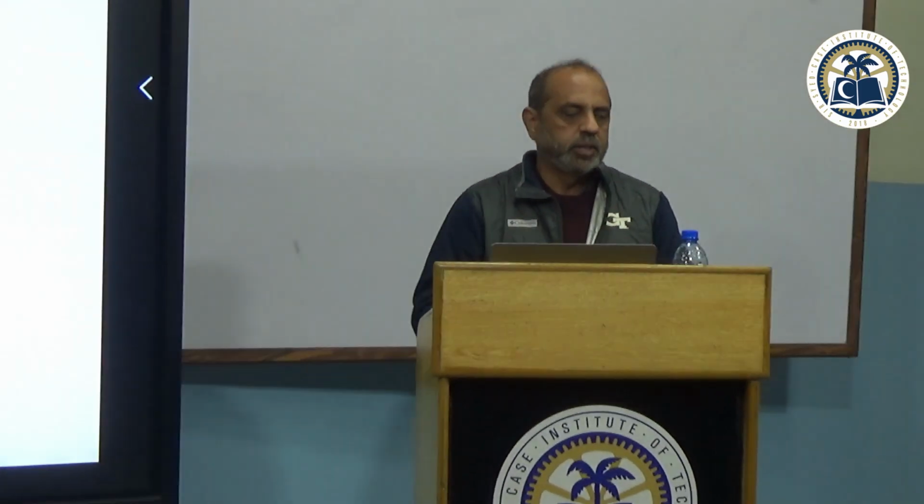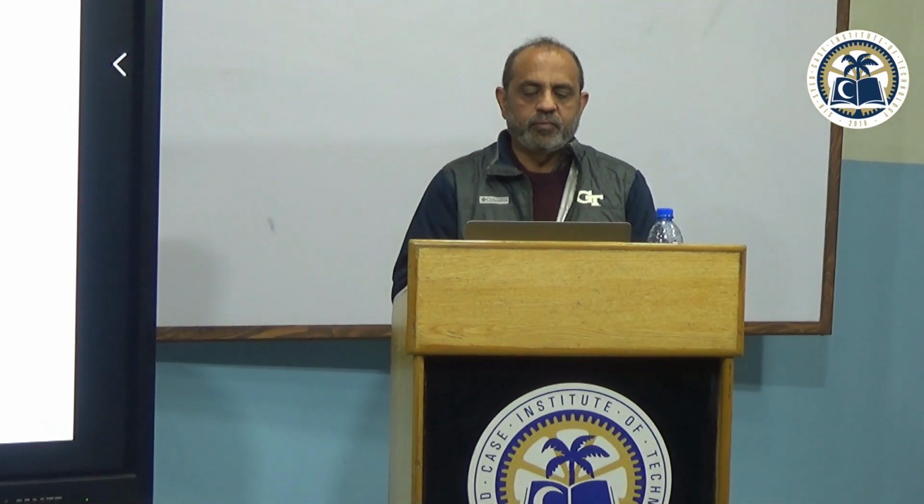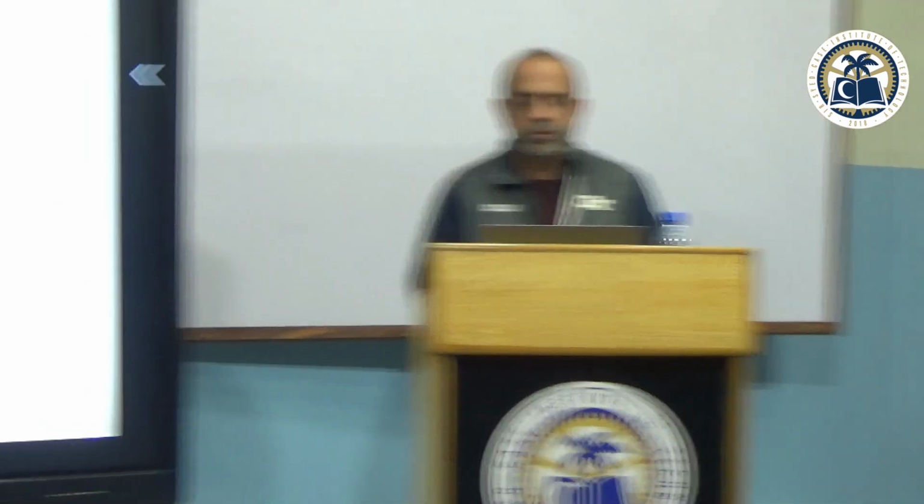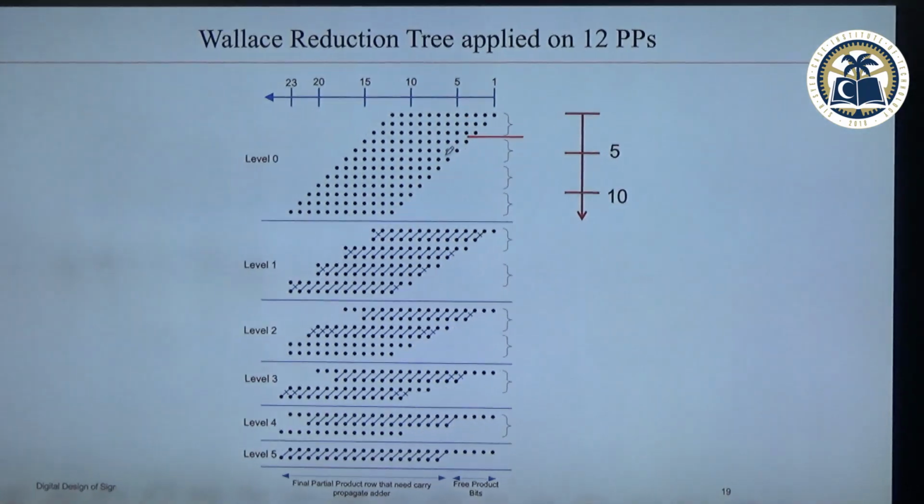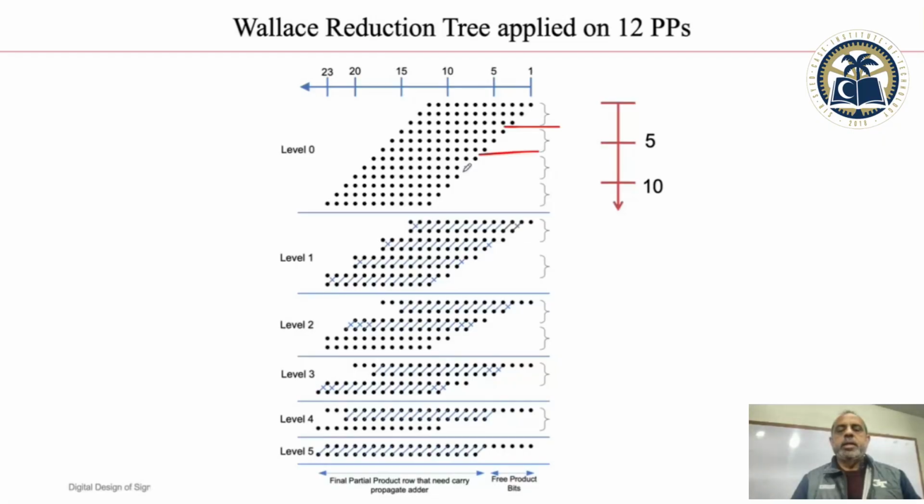But interesting is the Wallace tree. Wallace tree is where you have all the 3 layers together. So you have these 3 layers, and then you have these 3 layers, then you have these 3 layers, then you have these 3 layers. So in one go, putting a full adder layer would reduce them into 2, 2, 2, 2. So 12 would get into 8, right? 1, 2, 3, 4, yeah, 8. So from 12 layers with a full adder delay, you reduce it into 8.